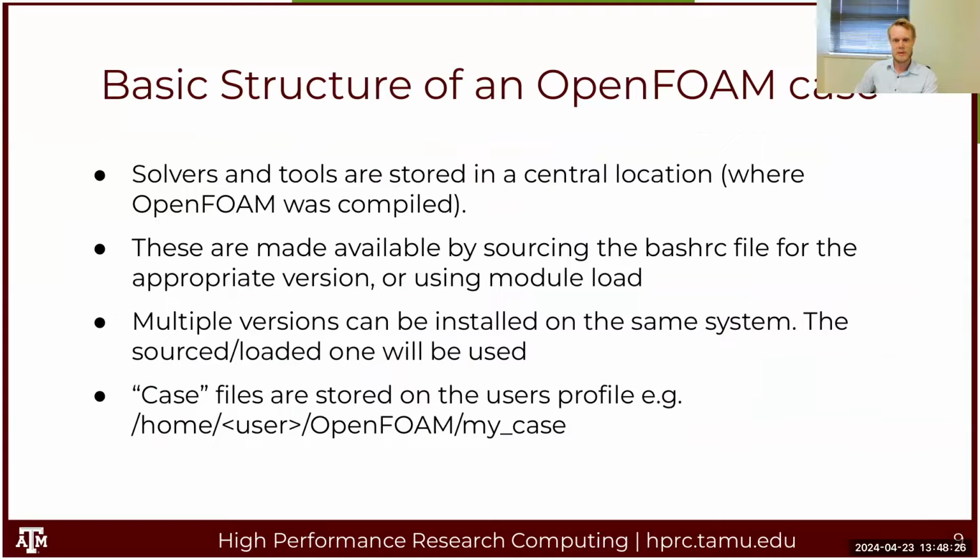This is basically what I just said. One point to make here is that there is a file called the bashrc that comes with each OpenFOAM installation that you have to source. And that's going to tell the terminal that you're currently in where to find all the components. So it's very important that that file is sourced, but I'll show you how to do that. And as I said, when you run OpenFOAM cases, you usually store them under your own profile somewhere. Home directory if you're on your own machine, or Scratch directory if you're on the cluster.